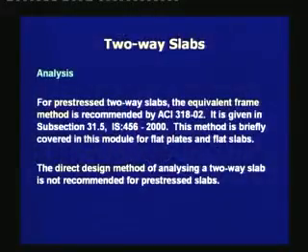In this lecture, we shall cover the method for flat slabs and flat plates and for two-way slabs with deflecting beams, which is given in section 31 of IS 456-2000. For prestressed two-way slabs, the equivalent frame method is recommended by ACI 318-02.